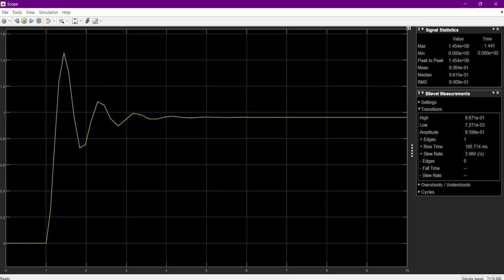Then we had some oscillations when we raised the gain of the proportional controller to more than 40 or 50. We started to have some transient response, and this is not good in terms of efficiency of the system. So in order to get closer and closer to the desired steady state response of the system, we may continue increasing the gain of the proportional controller, but this will not solve the problem without trade-offs. It will solve it with heavy trade-offs that we do not desire. So what will we do to compensate for this unneeded overshoot, and maybe undershoot as well?